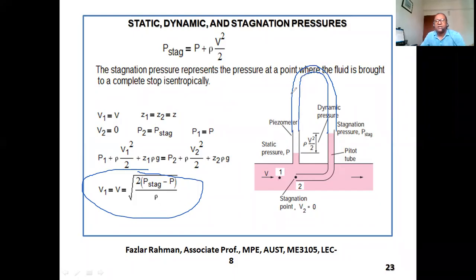Right over here, you put the manometric fluid, right? If the pressure is the same, both levels will be along this line. But the pressure on the right side is more, so what will happen? It will try to push up, and this side will be pushed down. This will become this much.